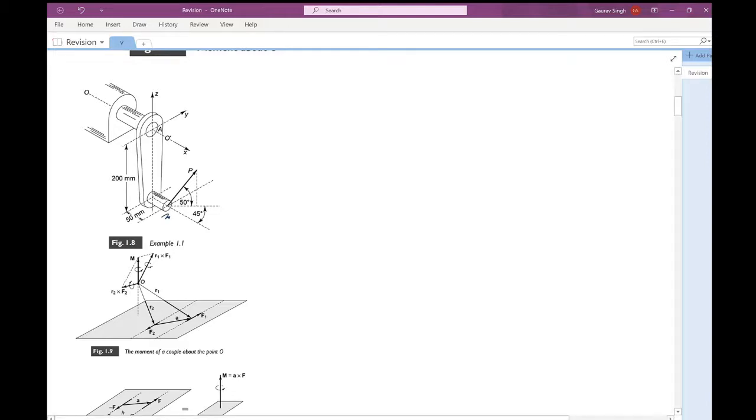This is a similar mechanism, and it's called a crank mechanism because you convert this rotational motion into a translation motion elsewhere. That mechanism is also used in automobiles, where a rotational motion eventually gets converted to a translational motion and the other way around. You'll see this in many mechanisms as you proceed in your course, and if we keep our eyes open and see how those mechanisms work, you'll see this in a lot of places.